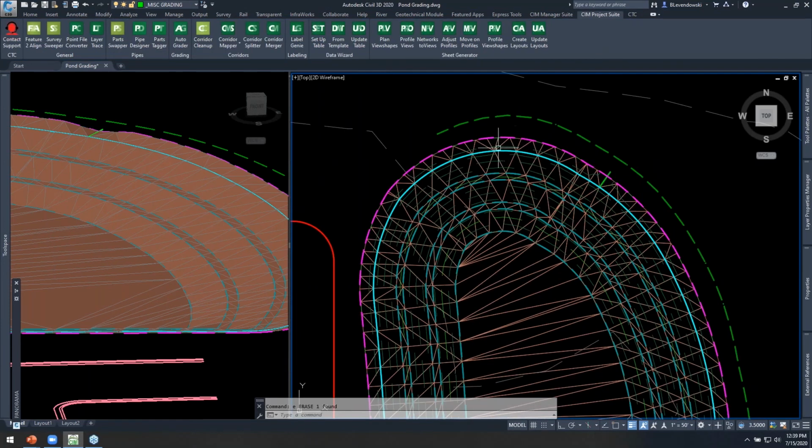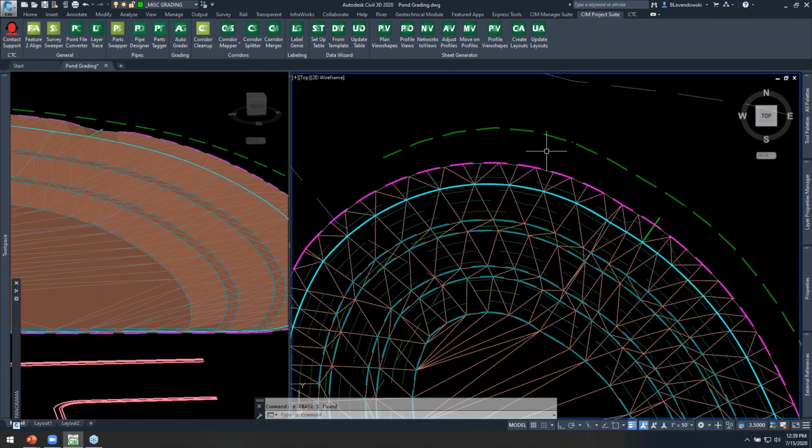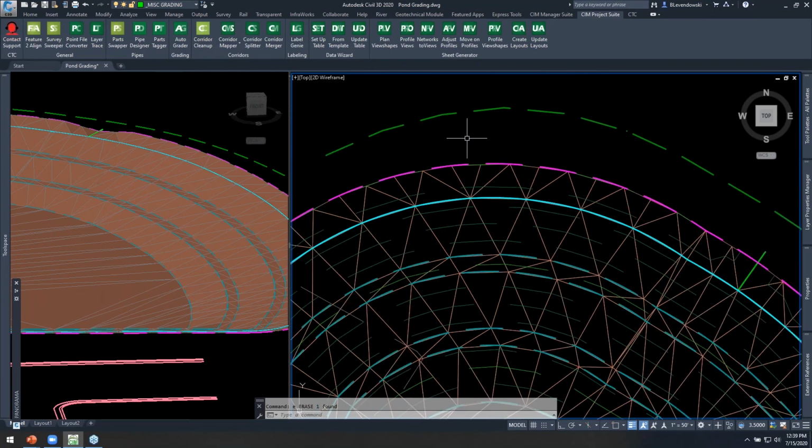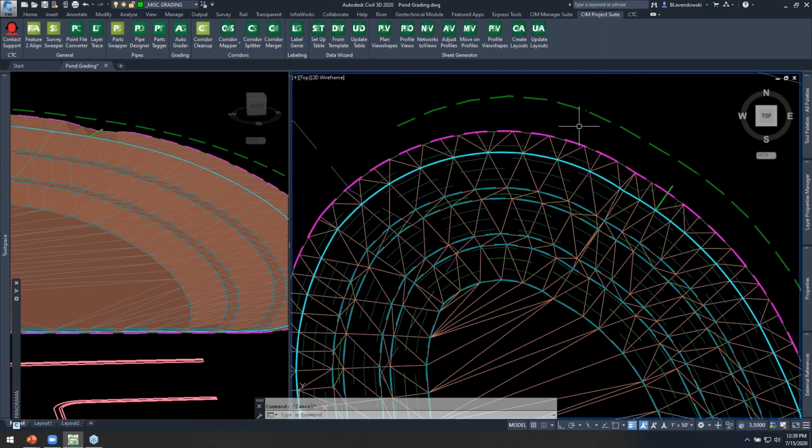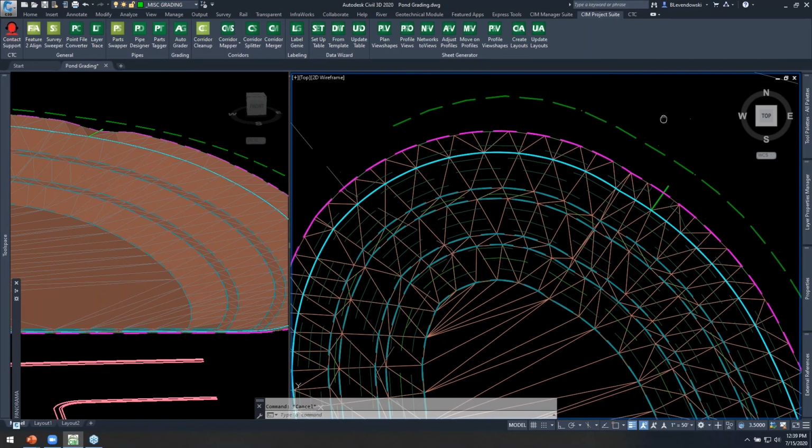So if you're stacking feature lines like this, we're working on updating the code on it where it can remember the child feature line that it was attached to. Basically, when you have families built on families, there's a refreshing thing there, but it works. You just need to get rid of that old feature line. Like I said, we're going to work on updating that there.